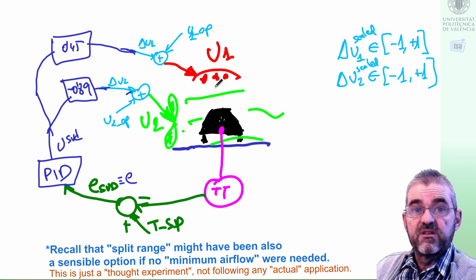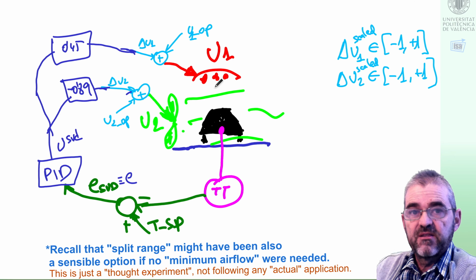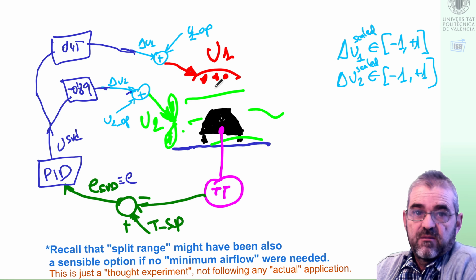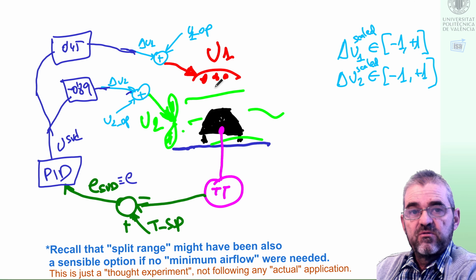If temperature set point is below my measurement, switch resistor off and switch the blower on. Indeed, that would be a common sense, very simple strategy. So I am not saying that this SVD load balancing is the thing that I would put in this process. That depends on what I am trying to do and the airflow set point I wish to pursue.